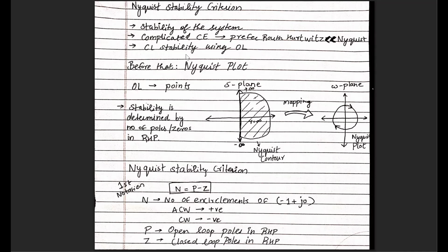You might be thinking, why are we using -1? I mean, shouldn't we always encircle the origin in most of the cases? Which I agree with as well, but I would like to explain to you how it works. The anti-clockwise direction is taken as positive and the clockwise direction is taken as negative.